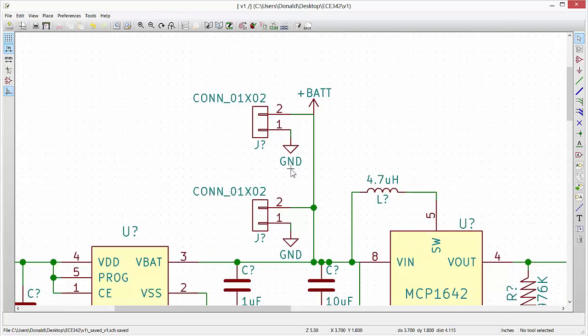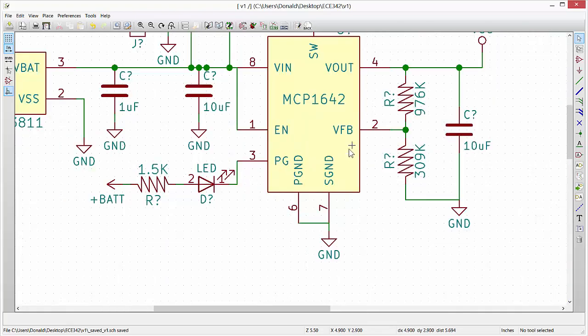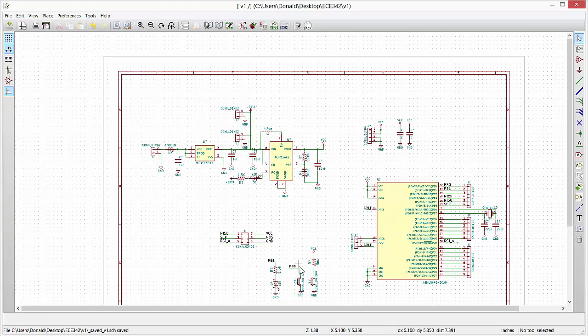The other thing is this particular connector that we're using here. We're going to have two different styles. One's going to be a JST connector, a 2 millimeter pitch JST connector, and the other one is going to be the actual battery terminals that are specified in the original PDF scan that went out about this project. I'm not sure, but I might want to change this component into two individual test points, each of those test points being one of those connectors, and then when I lay out the PCB, actually setting them to the proper dimensions there. Those are the things that I know of right now that I'm kind of curious about, and they might change even before we see the next video.